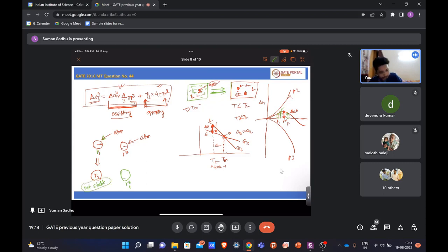But for this r star, now if you add one more atom, its radius increases and it is here. So now what is happening? Here the radius is increasing, but your free energy is decreasing. It is not increasing. After r star, as you increase r, your free energy of nucleation is decreasing, right?